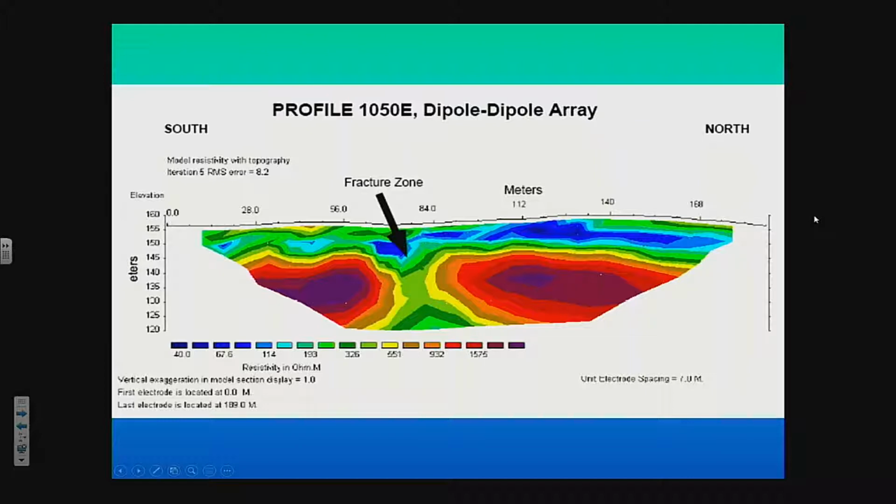So where on the graph, sorry, will it show us the water flowing? That would be the lower resistivity area, so probably this might be the saturated area. The blue is about 114 millimeters, so we see the blue would be where the water is.